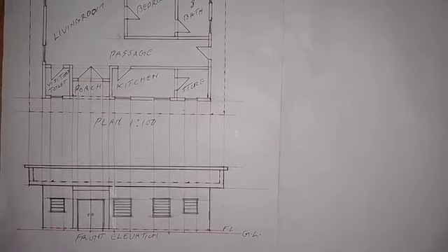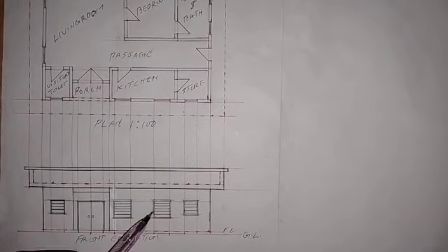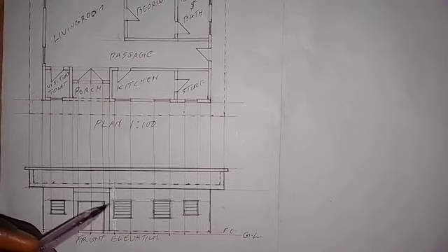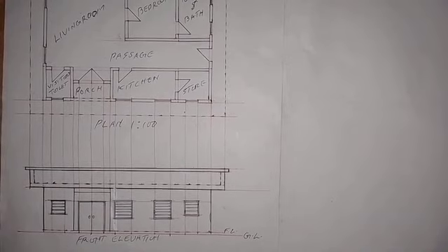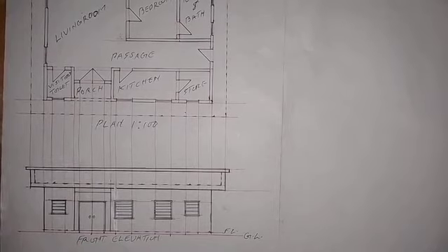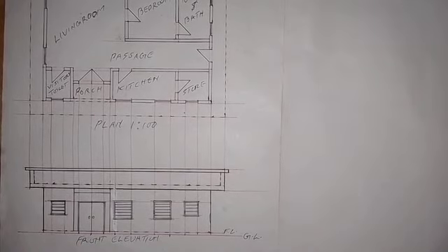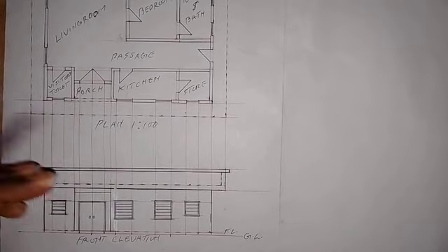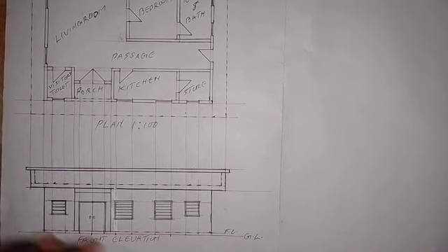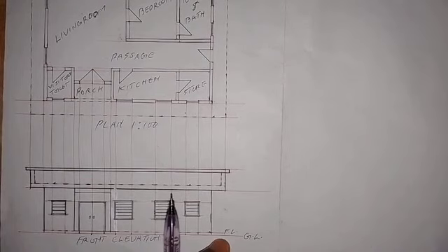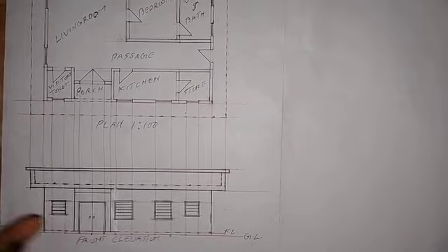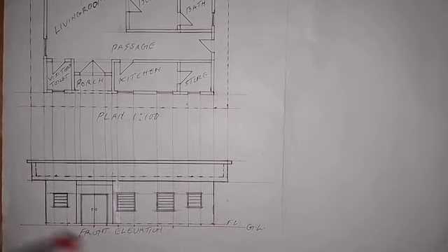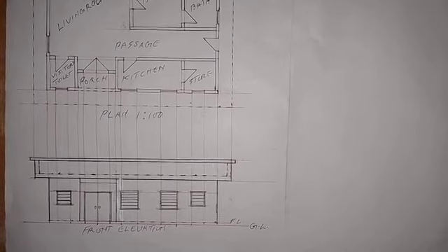Alright, so this is the front elevation. I produced the two windows that we have here. The dimension of these two windows is 1200 by 1200, that is 12 by 12, so that's what you see here. This is how the front elevation will look, and then you need to write here the plan, 1:100. That's the scale that we use. Then we have the front elevation here. Don't forget to indicate the floor level and also the ground level. All these things are part of what will be taken note of when they are preparing the marking guide, and also to mark your work here in building drawing.